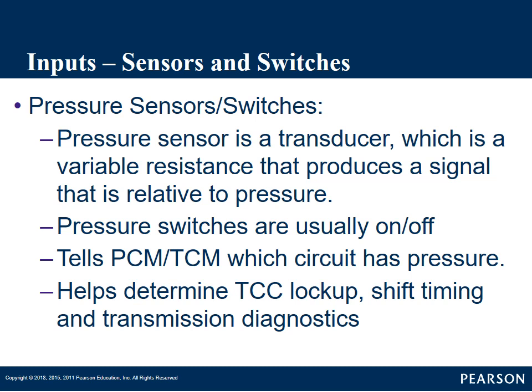They're monitoring that pressure, and we'll talk about this when we get into adaptives. The transmission monitors the time from when it commands a shift to when the shift happens. The computer commanded the shift to happen at this point, and it took this amount of time before the shift actually happened.